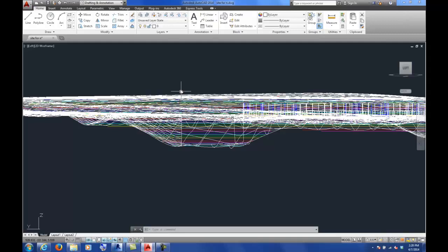So what you'd have to do is go to each contour line and move it up to the correct elevation. If it was all a straight line, it'd be all at 0 or at some kind of plane. If you had actual contours that were 734, 733, and so on, you'd have to physically move them in AutoCAD first up to those locations in the z-axis, and then we could bring it into Revit. Is that regular AutoCAD? This is regular AutoCAD, that's on the screen here.